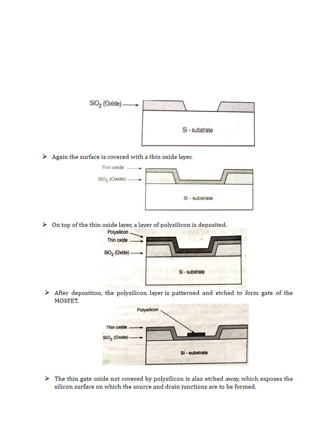Now the oxide which you see at the corners, where the window has been created, is the thick oxide in the corners. These are also known as field oxide. Field oxide is the oxide region other than the gate oxide. So the next step is the growth of gate oxide.